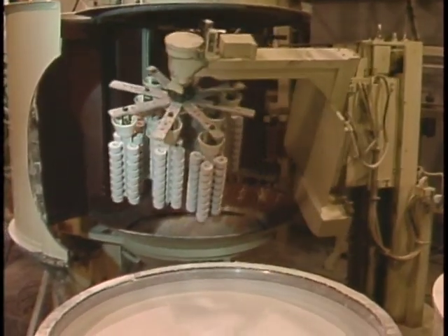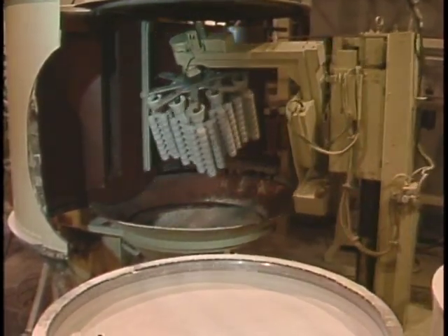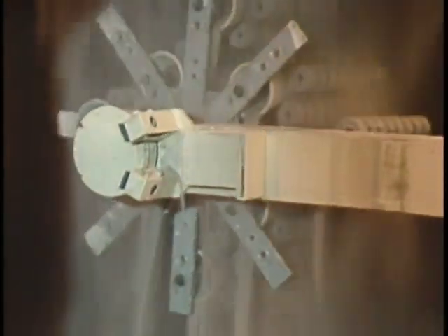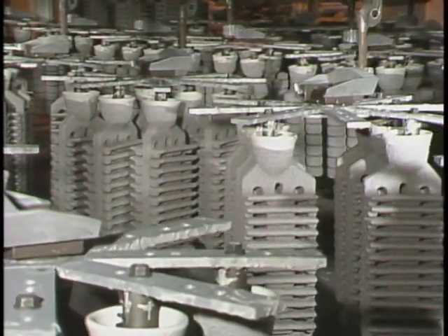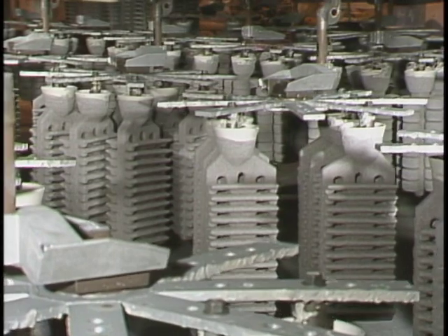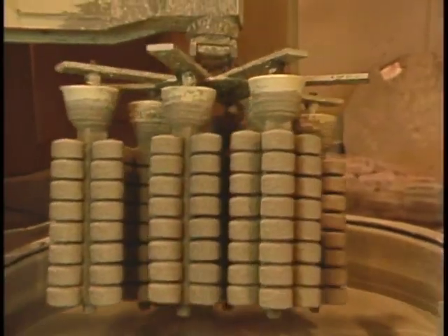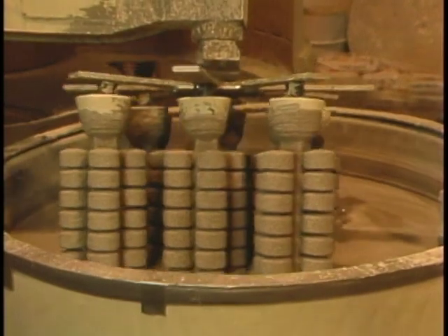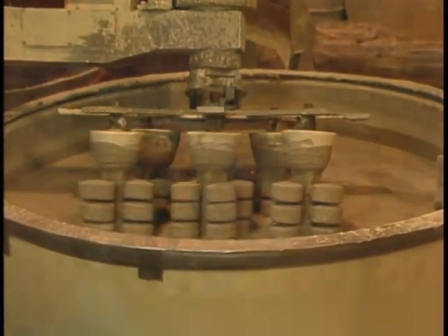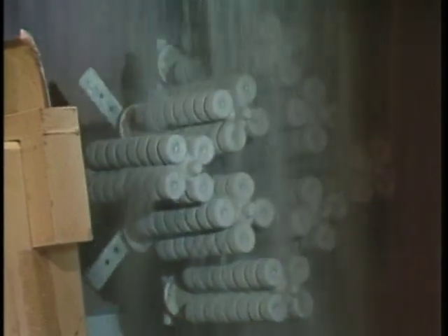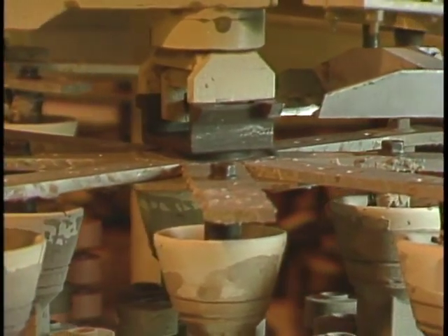The wet assembly is then inserted into either a fluidized sand bed or a rainfall sander where the sand particles adhere to the wet surface. Care must be taken to make sure that every detail of the assembly has been properly coated. The assembly is then placed on a rack to be dried under carefully controlled conditions. Additional coats of progressively coarser grades of material are then applied to the assembly. Finally, the desired shell thickness is achieved. The shell production process lends itself very well to automation. Robots have been developed to carry out the shell build-up sequences.